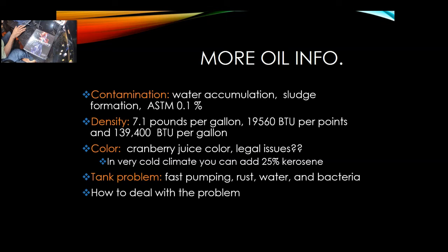How to deal with the problem. If you have any kind of gumming or problem in the tank, you have to clean the tank, and there are some specialized companies who do that. If you have water in the bed of the tank, you have to empty the tank and get rid of the water.